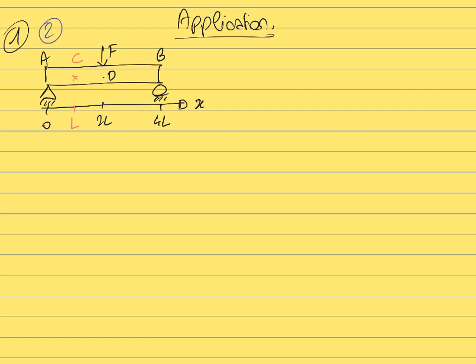So we identify the reaction, and in step 2, we identify the unknowns. So we identify what are the unknown reaction forces applied by each of the supports. So this is where you need to look at what are the supports to which the system that you are isolating is attached, and you need to draw those supports so that you can define whether those unknown forces are going to be defined as pointing upwards, downwards, towards the left, towards the right. So in this case here, the member is attached to two supports, one pin and one roller on the right.